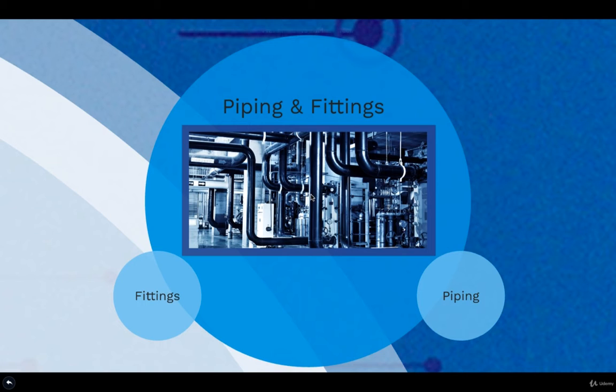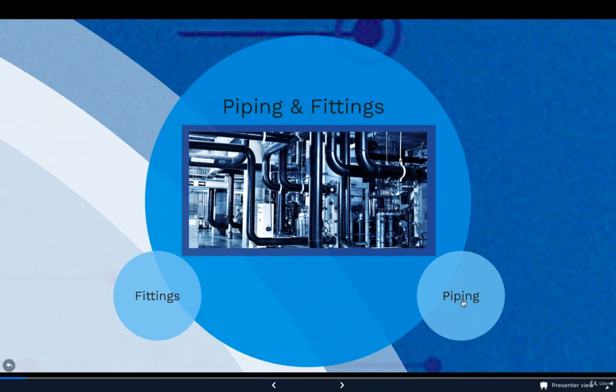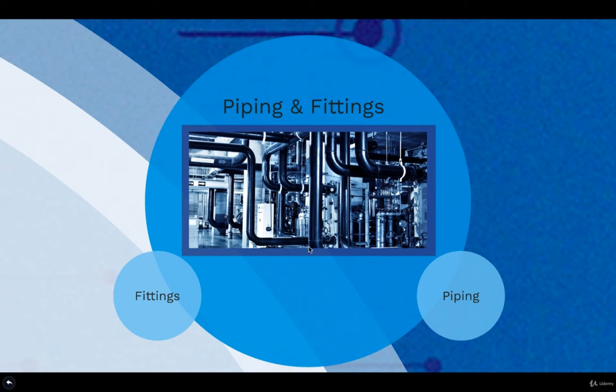Talking now about fittings. We saw already how to model pipes and so on, but fittings are essentially needed, for instance, in order to move this pipe through a 90-degree angle. You will need a fitting which is called an elbow. You also need these suspenders right here. Also, you have valves, you have pipe measuring devices, you have plenty of other fittings, and we're going to see